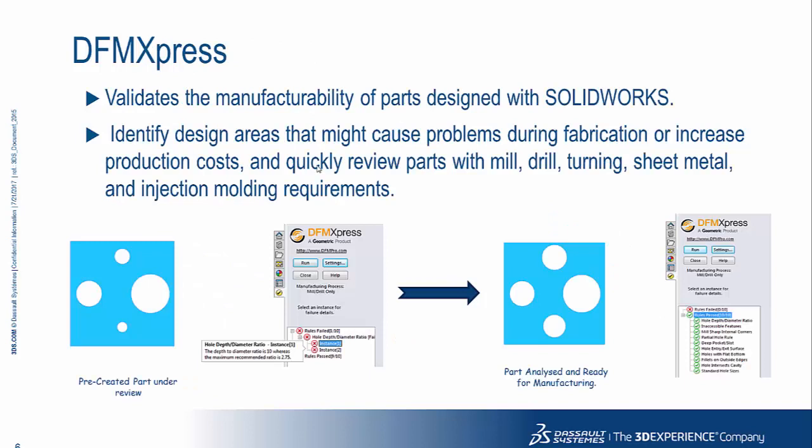Then we have DFM Express. So what is DFM Express? DFM Express validates the manufacturability of part designed with SolidWorks. So what if I have some tools available at my workshop, but it is not known by the designer, and designer creates fantastic designs. So suppose in this model, what I can see is that there are some holes created, but at my workshop I have limited tools which are larger in size. So with that, this DFM Express, it will show that these holes cannot be created.